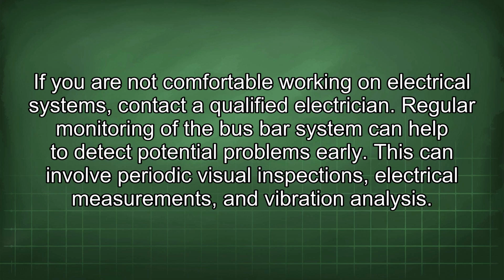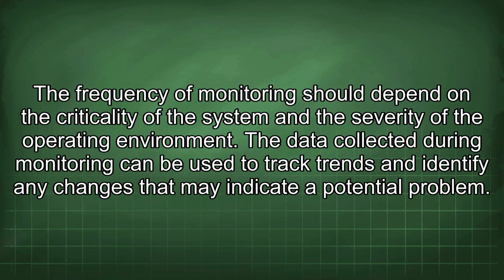Regular monitoring of the busbar system can help to detect potential problems early. This can involve periodic visual inspections, electrical measurements, and vibration analysis. The frequency of monitoring should depend on the criticality of the system and the severity of the operating environment.